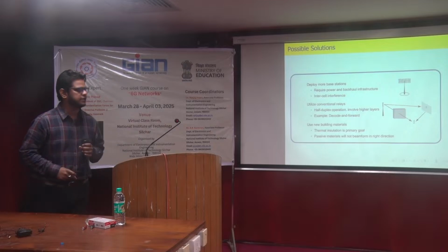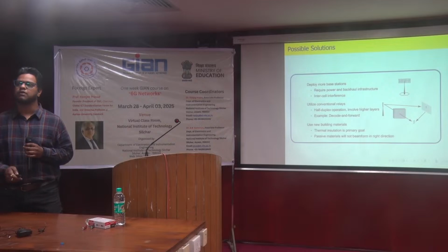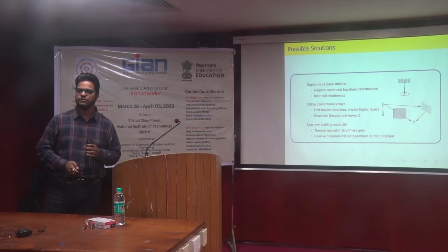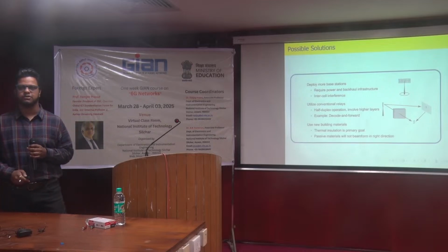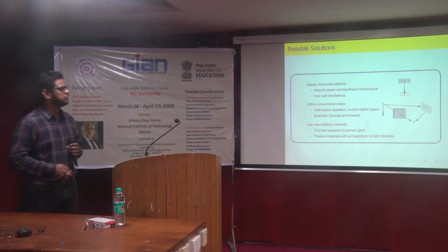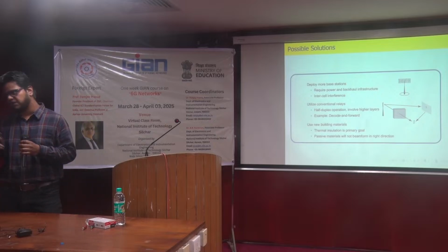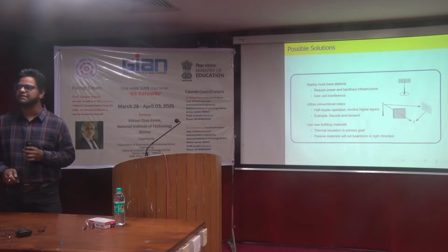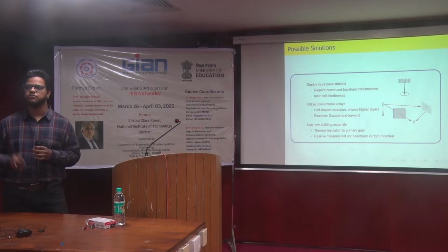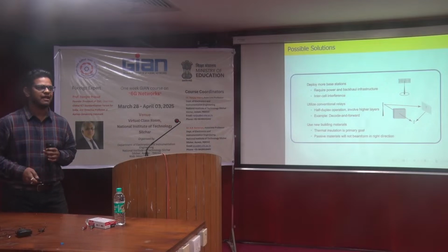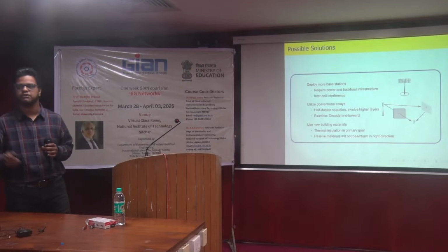And usually they operate under two different protocols: amplify and forward, and decode and forward. The problem with the amplify and forward protocol for the relay is that it amplifies the noise itself, so that reduces the signal to noise ratio and degrades the performance. The other is the decode and forward protocol of the UAVs, which requires complex circuitry on the UAV itself, which makes the UAVs more bulky and requires higher battery power, which again limits their operational time or flight duration.